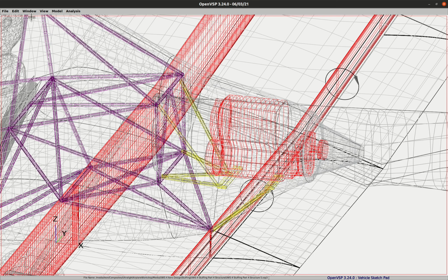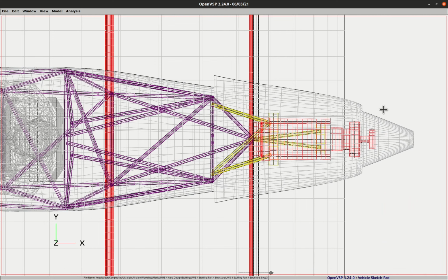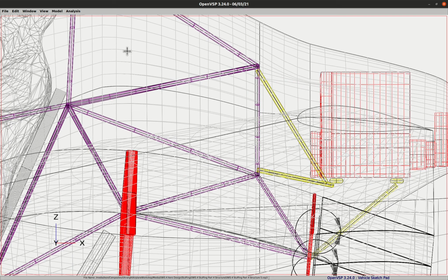And of course, twisting from the top, let's view that. Any torsional loads like this are not going to be handled by these bottom tubes. They've got to be handled by these tubes here. We have point loads that the fuselage has to handle here, here, and here.